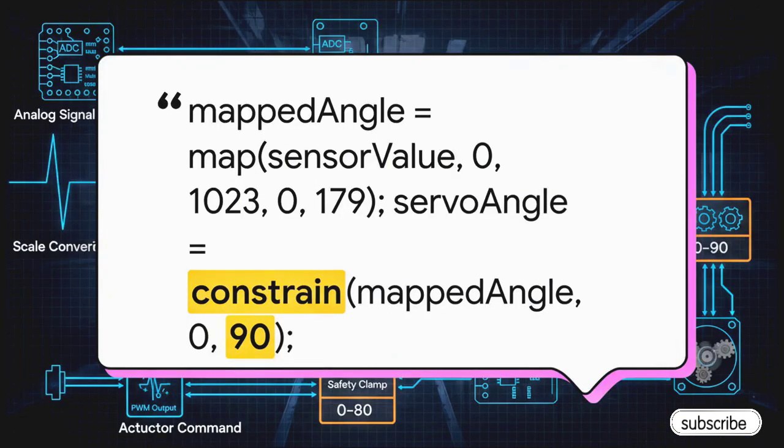And right here, you can see the direct implementation of that logic in code. That map function is doing the scaling for us. It's remapping the input range, 0 to 1023, to our desired output range of 0 to 179. Then, that constrain function kicks in. Think of it like a safety clamp.